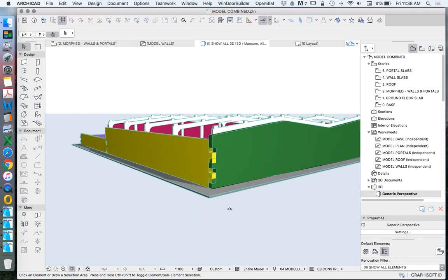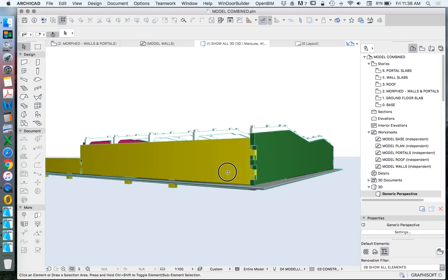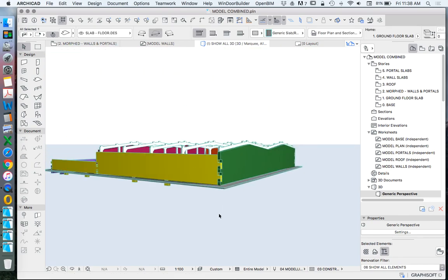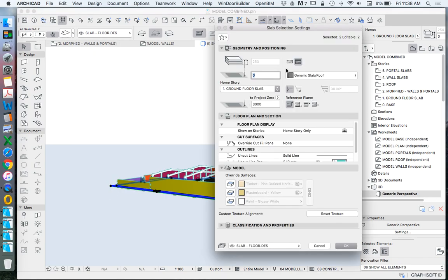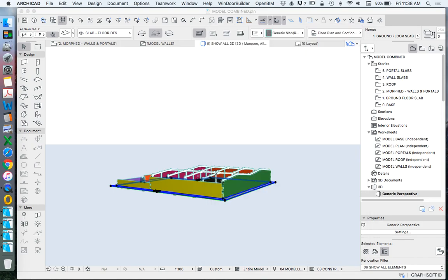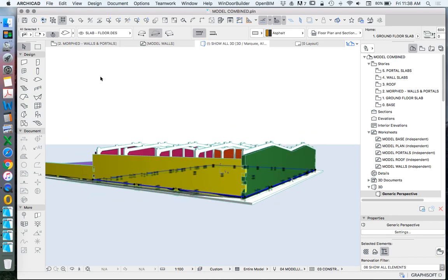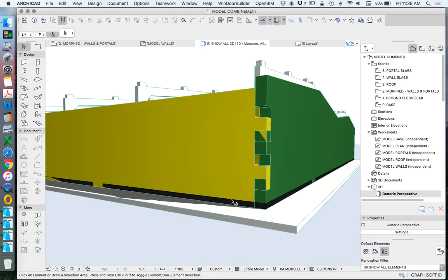So we can see straight away some of them aren't working. What's that based on? Just when we rotate things, it's very common that they're not quite right. So we need to get a lot of these all lined up. So we have these slabs here. Now I should be able to do this in my head a bit. We know that we need this to be a 300mm slab, and we want this to be set down minus 300mm from the top. Whereas this slab, we want to be 600mm, and we want it to be aligned with the story. So that's working nicely.